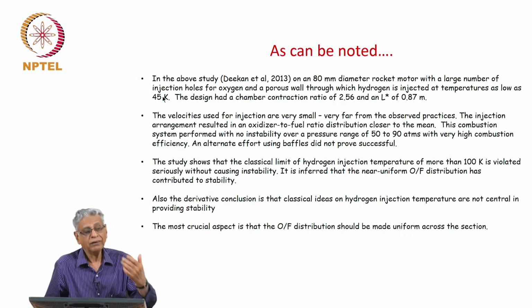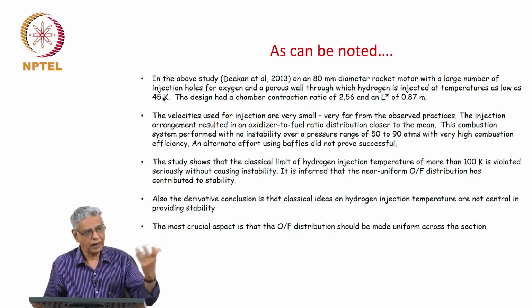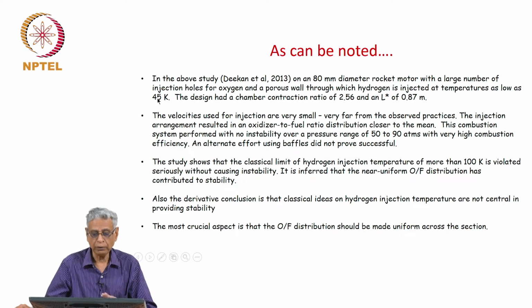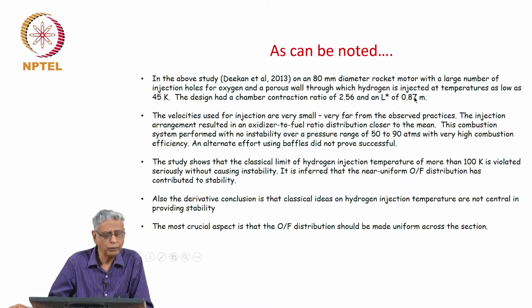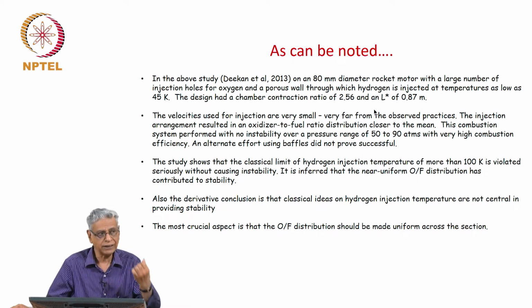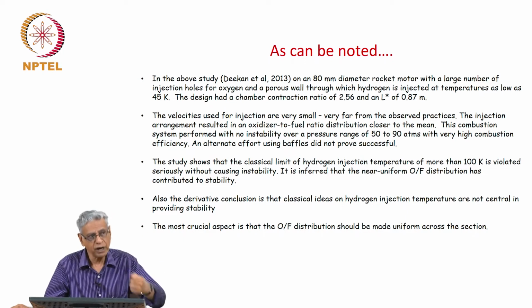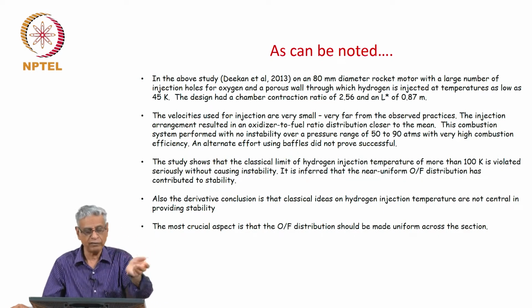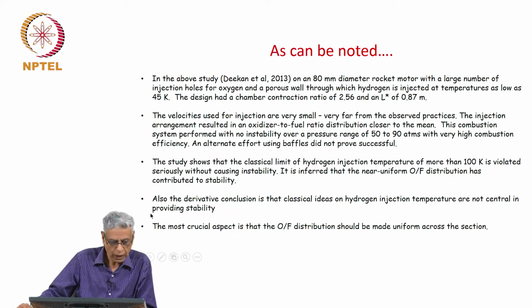And that temperature, for example, for injection in the engine which we built at LPSC, the injection temperature is more than 100 Kelvin. And you see, even at a temperature of 45 K, they found it to be stable. It has a certain contraction ratio and so on. And therefore, it looks like what drives the instability is simply the fact that the lateral mean flow, on which the acoustic flow field really works, leads to coupling, which is unfavorable. Okay. I think the most crucial aspect is that the LOX distribution is made uniform across the cross section.